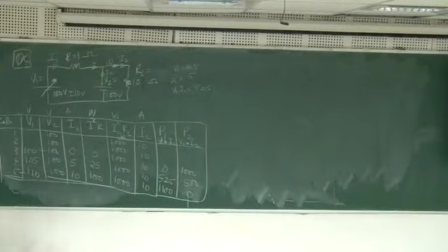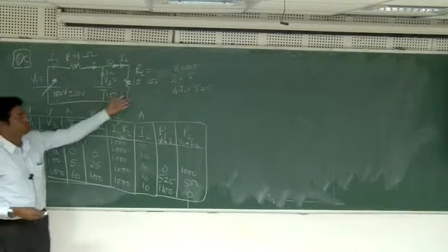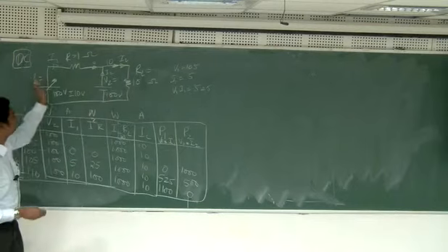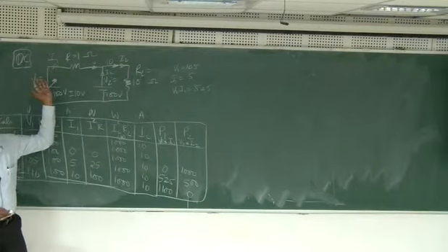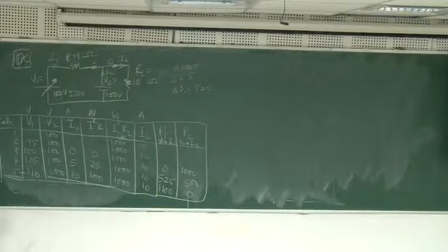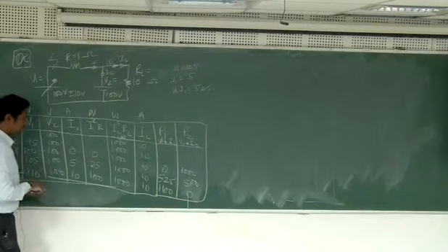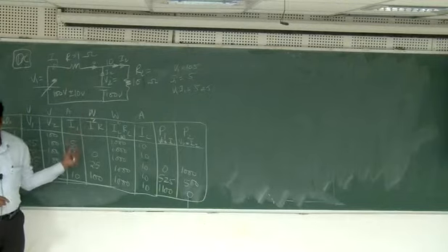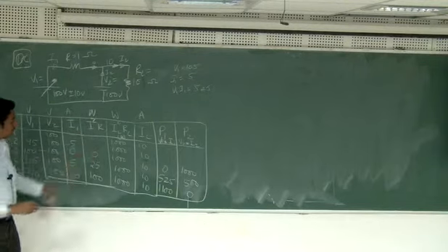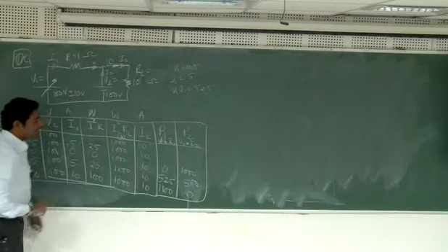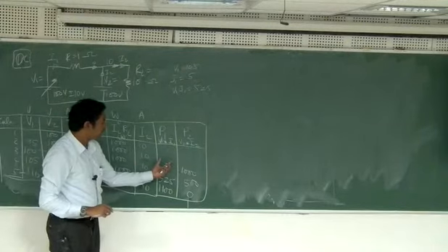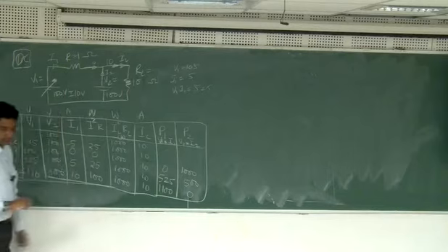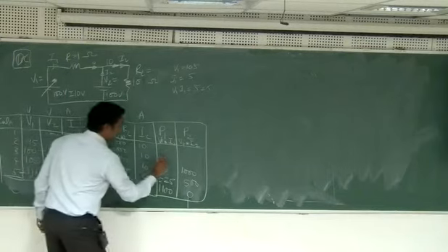Okay. So the reverse happens if this is 95. So you will notice that now the load current does not even come into picture. If this is 95, the power starts flowing in reverse direction. So the current, I'll write it as minus 5, whereas for I square R, because the square is there, the minus will get cancelled, and this still will be 25 watts lost. And what will be the V1 into I1? It will be minus 25.